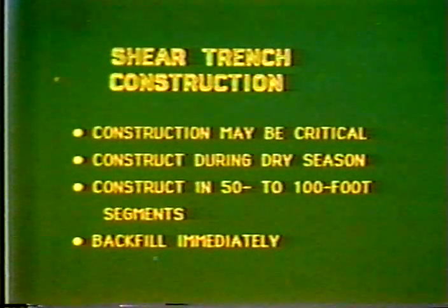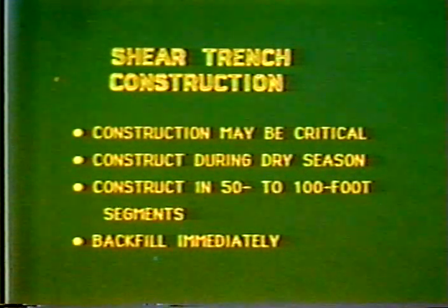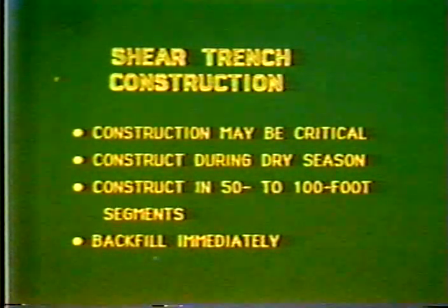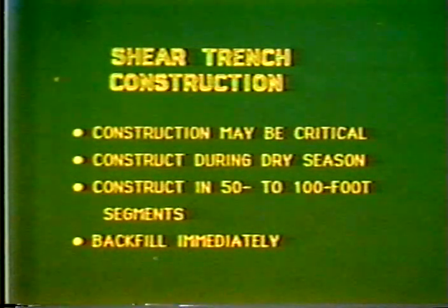But let's go on with another case history. When you're doing shear trench construction, it's very critical in that you're digging near the toe of the fill, and you may have the whole thing come down on you. So there are some guidelines here. First, construct it during the dry season of the year, when the water tables are low and there's not much surface water running into the slide area.